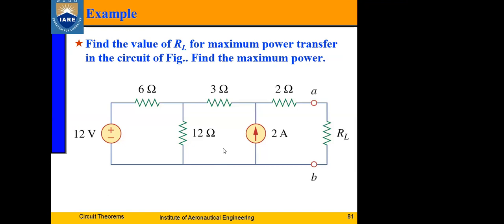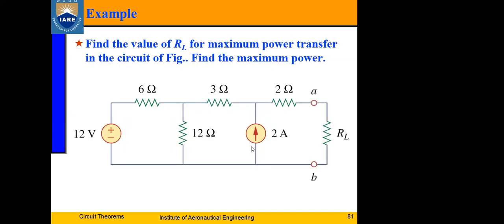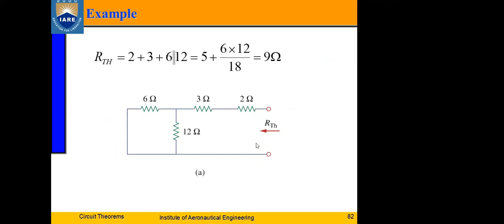Right here, I already created a file once on the desktop. I can open it directly. Go to library, then systems, specific technology, fundamental source, this voltage source.